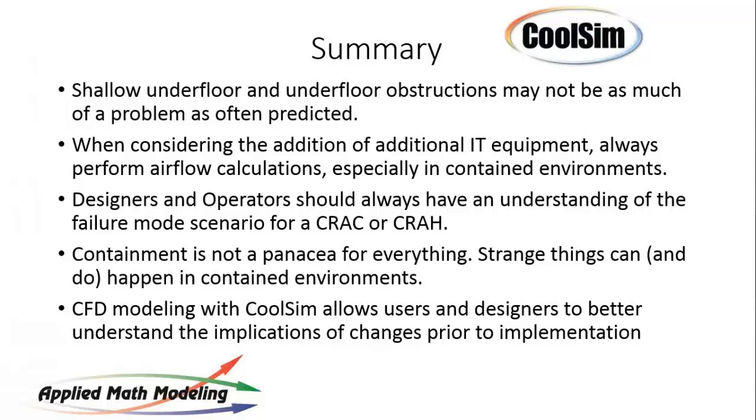Now, there are options like rear door heat exchangers, both forced and naturally convective, that remove the heat at the source. And in supercomputers, they pull the heat out inside the cabinets themselves and then reject it to the atmosphere. So there are those methods. But in conventional, off-the-shelf kinds of designs, like the ones we typically run into, you're containing one or the other.